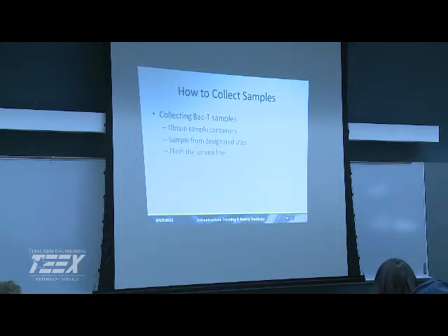Okay, all right. So you're using a DPD method, because you really should be using an EPA approved method, and DPD is an approved method. We talked yesterday about that. There's now a strip method that's supposed to be approved by EPA, which I didn't know about. I'm an instrument guy, and of course, when you come out of a big system, everybody's got a pocket colorimeter. I got an app on my phone. There you go. You almost could stick your phone in there and figure it out. Heck, you could probably get pH, alkalinity, all that.